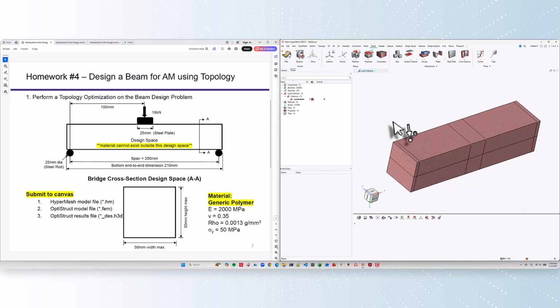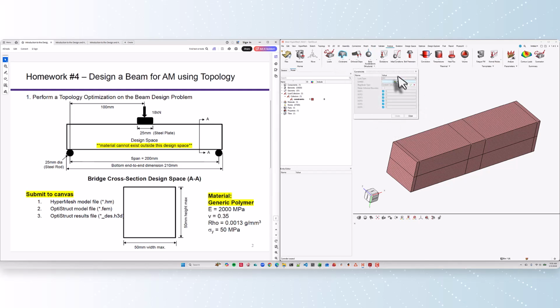So rotate it around. And to do boundary conditions, I need to go to the Analyze ribbon, and then you'll see constraints. Okay. First thing I need to do is pick the left line of roller nodes. The easiest way to do that when I'm in the node selection is to hit the 3 dots and use the bypath option. It probably says follow edges for you. Uncheck that because you don't want to follow edges. I want it to go straight across. So I'm going to pick the bottom node and then the top node, and you see it automatically picks them all along. It's just a fast way to pick them. It's called bypath. Okay, I got the nodes that I want.